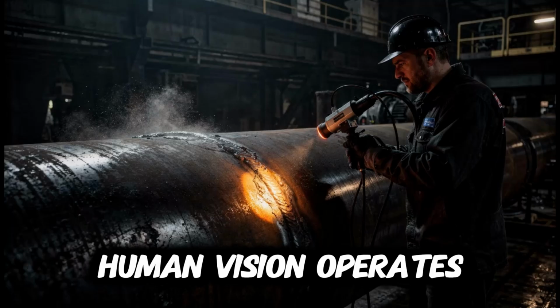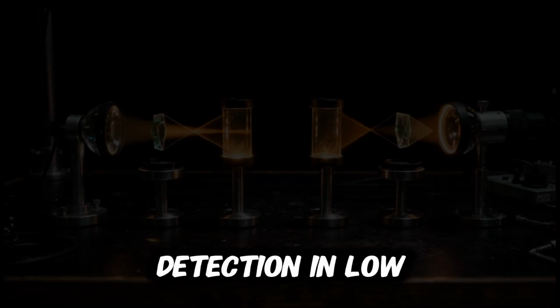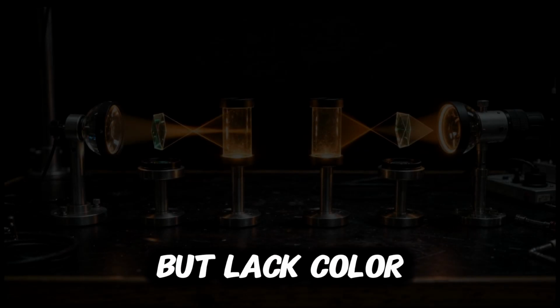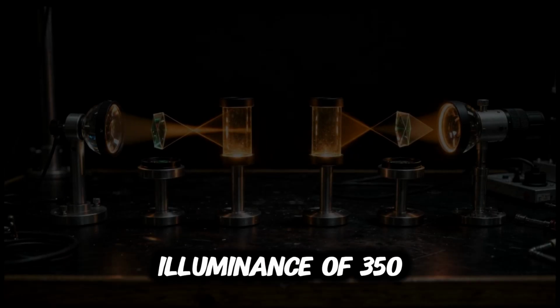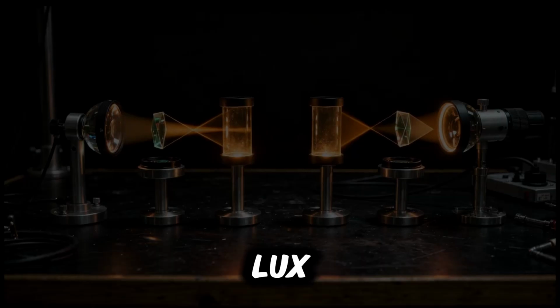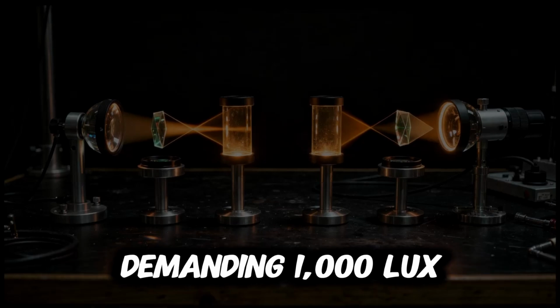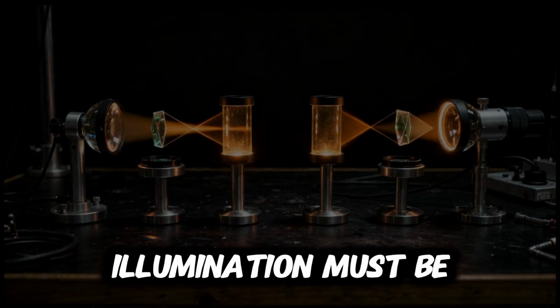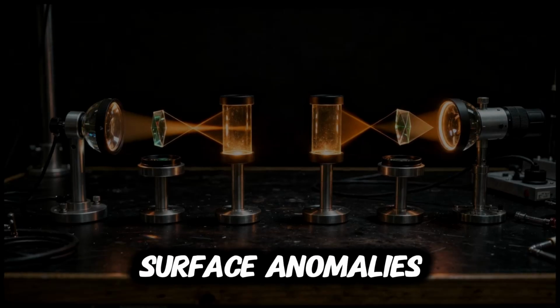Human vision operates through the interaction of light with photoreceptor cells in the retina. Cones provide color discrimination and detail recognition under adequate illumination, while rods enable detection in low light conditions but lack color sensitivity. Effective visual inspection requires a minimum illuminance of 350 lux on the inspection surface, with critical applications demanding 1000 lux or higher. Illumination must be uniform and diffused to prevent glare, which can obscure surface anomalies.